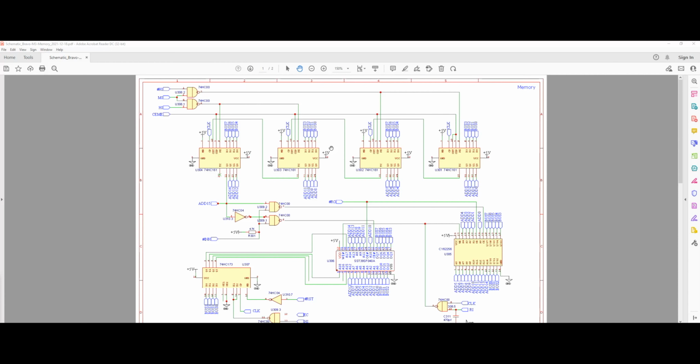However, here we have a dedicated binary counter for addressing our memory, and there is a reason for that. Essentially, having a dedicated memory address register enables us to address memory whenever we need it, while the program counter stays at whatever step it should be.